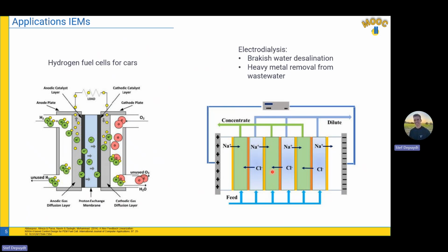this is the ion receiving end. There sodium will arrive and chloride will arrive, and these sodium and chloride are now stuck here because the sodium cannot transport further because suddenly there is an anion exchange membrane. This way, with electrodialysis, it is possible to create concentrated compartments with ions and diluted compartments with ions. So this way we can desalinate brackish water.